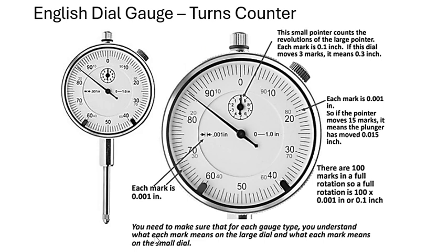You have a gauge block stack, and you know the exact height of the gauge block stack, because each block has a specific height, which is your specification. So if you know the sum of that gauge stack, you can either subtract or add, depending on the height of the object you are measuring using this dial gauge. That's how it works.